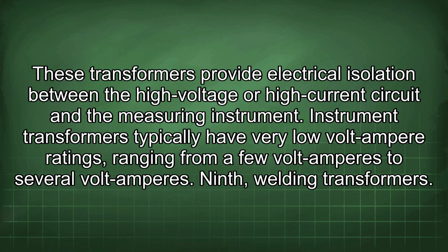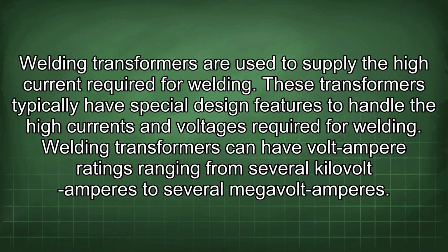Ninth, welding transformers. Welding transformers are used to supply the high current required for welding. These transformers typically have special design features to handle the high currents and voltages required for welding. Welding transformers can have volt-ampere ratings ranging from several kilovolt-amperes to several megavolt-amperes.